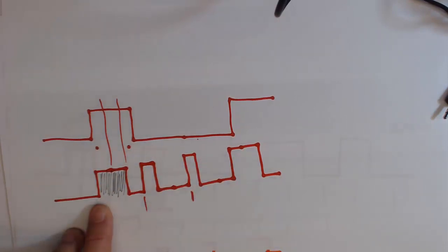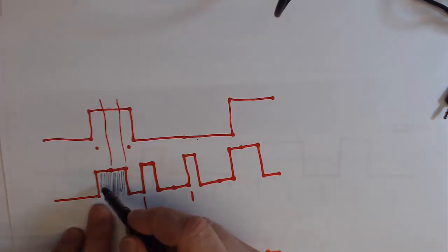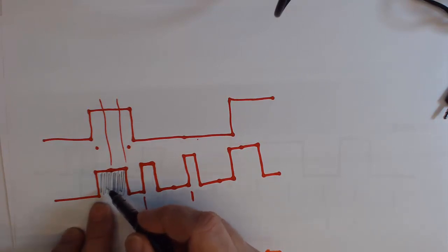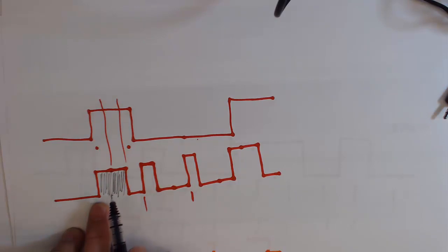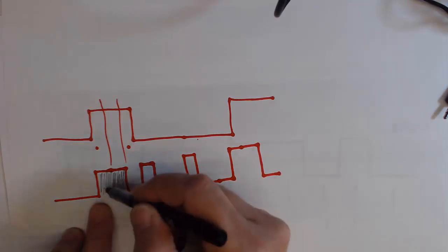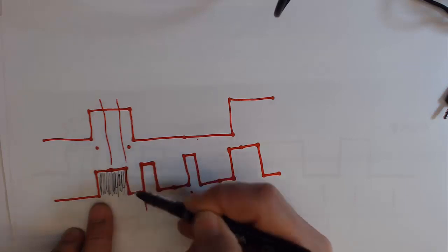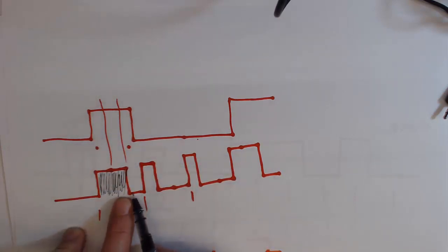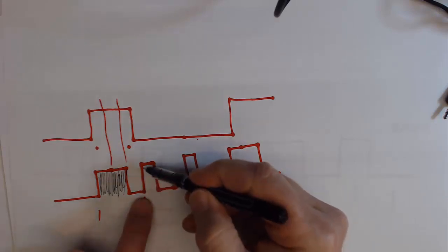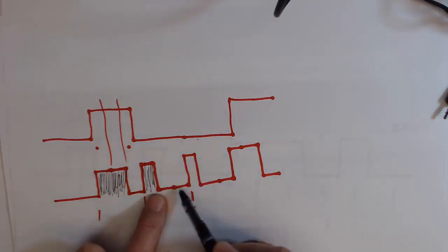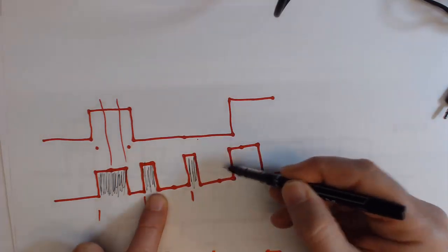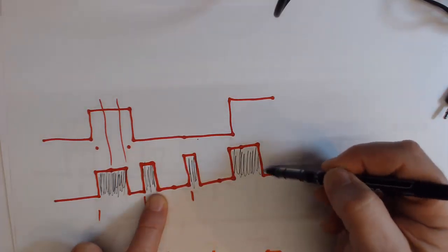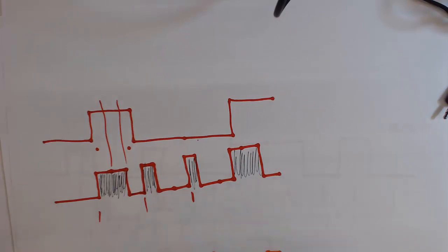And so the microprocessor is bit banging this out. It's going to put out a square wave that's in the range that the tape can pick up. In the examples that we did for the software, it's a 2 kilohertz burst. So when we want this to be a logic 1, we're going to put out a 2 kilohertz burst square wave. We want it to be a logic 0. It's going to be nothing, a pause. So then this would be another 2 kilohertz square wave, and then a pause, square wave, pause, and that's all square wave. So we can hear this on the tape.